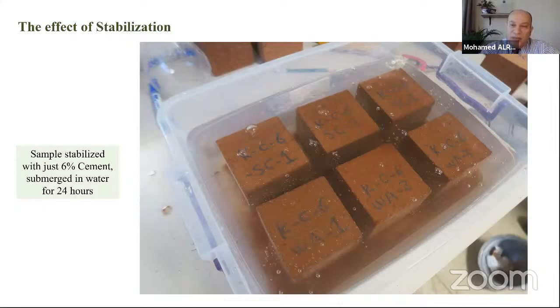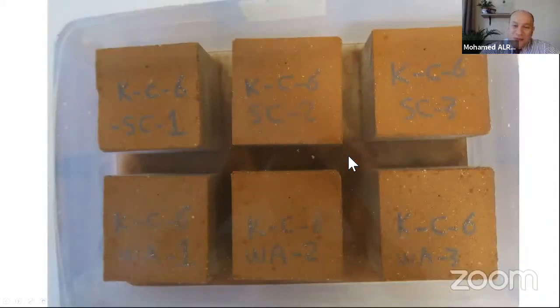We brought a local soil from the southeast part of Turkey and subjected it to stabilization with cement for just 6%. And could you imagine, we left it for 24 hours fully submerged in water. And this is after 24 hours, fully submerged in water. It didn't dissolve or deteriorate, no.